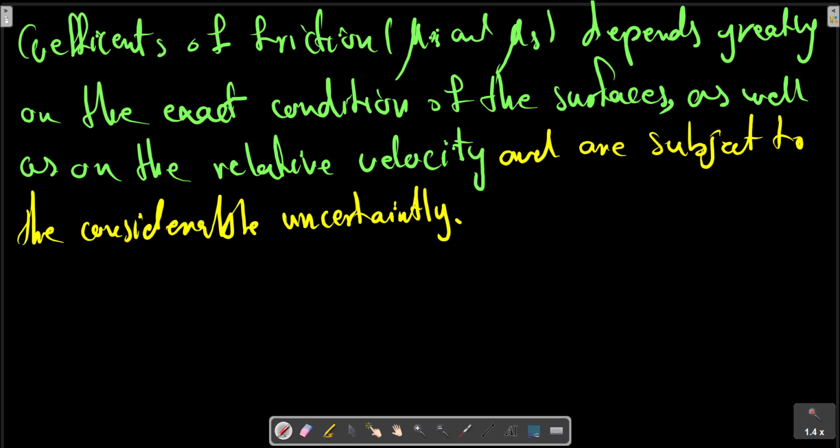In the engineering literature, we frequently find expressions for maximum static friction and for kinetic friction written simply as μN. It is understood from the problem at hand whether maximum static friction or kinetic friction is described. Although we will frequently distinguish between the static and kinetic coefficients, in other cases no distinction will be made and the friction coefficient will be written as mu itself.